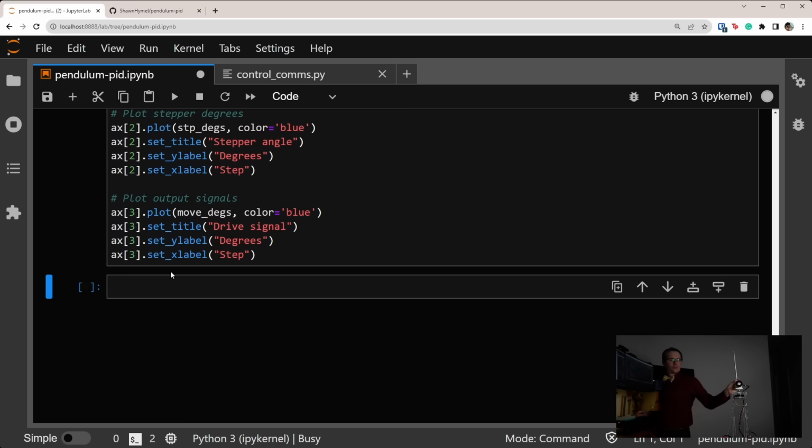Ooh, what just happened there? Let's try that again. Oh, it's oscillating badly, and then it whips around. Let's go take a look at our plot. And here we go. Sure enough, it's unstable. You can see it bouncing back and forth and getting larger and larger before it loses control. That's unstable. That means that Ki is definitely too large.